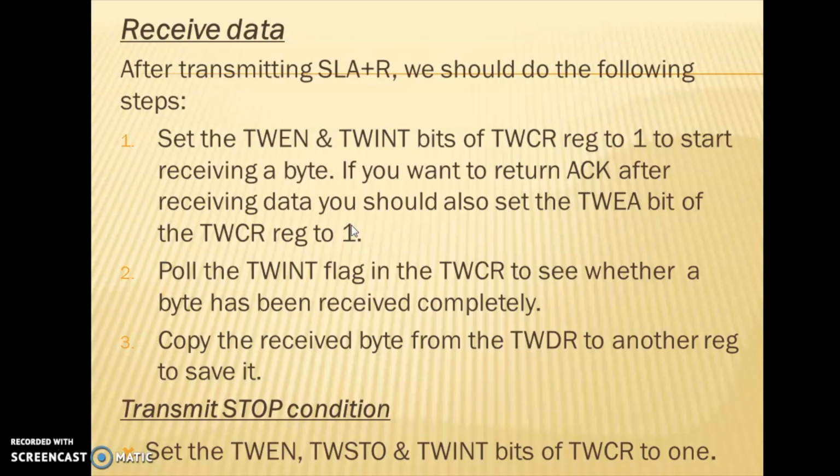If it is set, then copy the received byte from the TWDR to another register to save it, or give it to a port to display it. You can do anything. Then after the completion of data reception, we will send the stop condition. So this is all about receiving data.